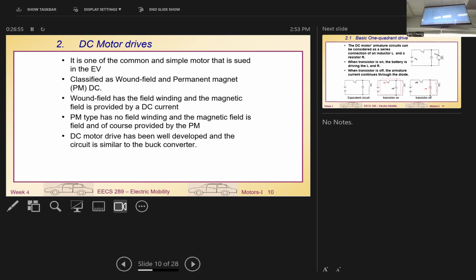There's a technique in motor drive systems we call overdrive. We tend to operate the motor at a very high rotational speed. In this case, we need to give up on the torque, because at high speed we cannot have such high power. So we usually reduce the torque; with high speed, the motor torque will be reduced. Simultaneously, we have to reduce the magnetic field current to help reduce the motor torque, because if the current is still too high, then you overdrive the motor anyway.